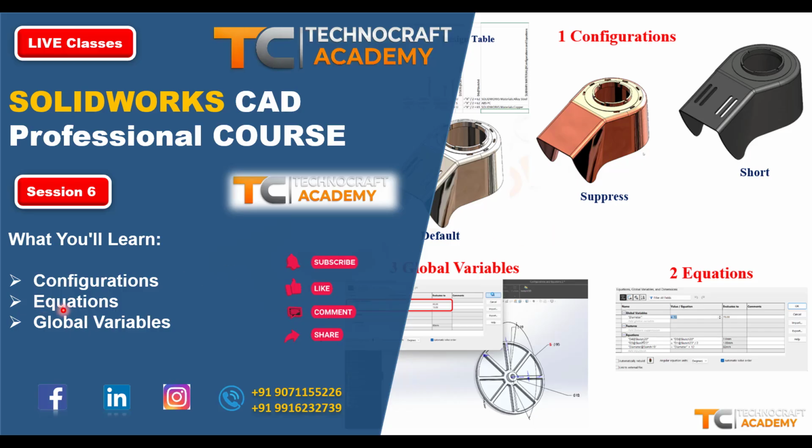Now, finally, the equation. You can assign equations. Here you can see there are multiple equations I have added to particular dimensions. Assume this is the outer diameter. If I want the equation inner diameter plus outer diameter divided by 2 plus a value, you can directly assign that equation here, and it will take that value and use it as an equation. That's all about the description of this one.